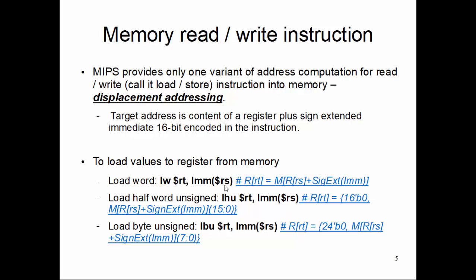But remember, in the last lecture we also talked about register usage convention. If you don't follow the convention, you are probably going to hit some unknown issues, because the rest of the software system assumes that convention of register usage. So use the registers with the convention. The register within the round brace contains your base address. That base address will be added to this offset value, which is encoded into the machine code in 16-bit 2's complement form.